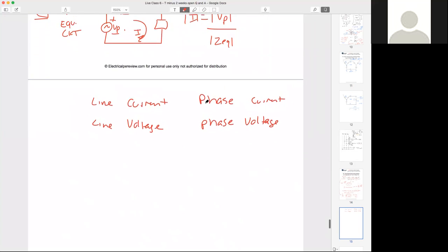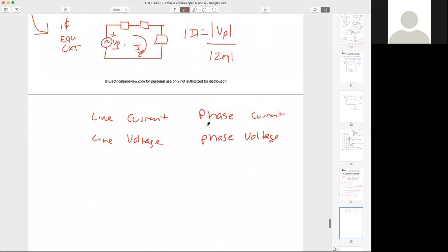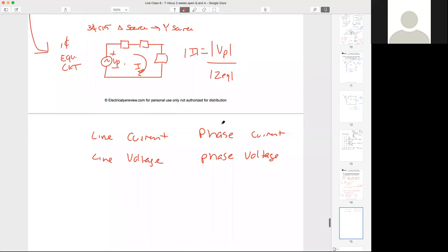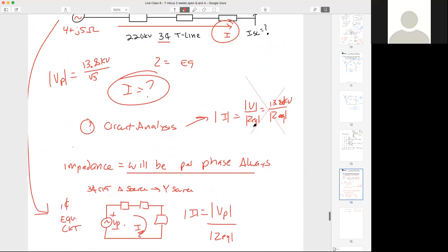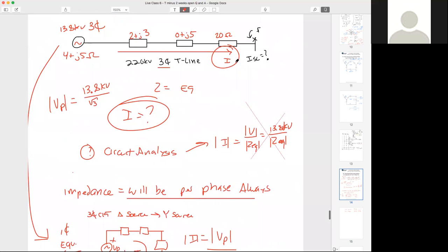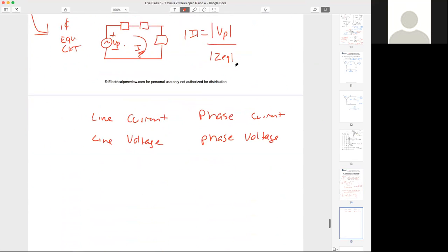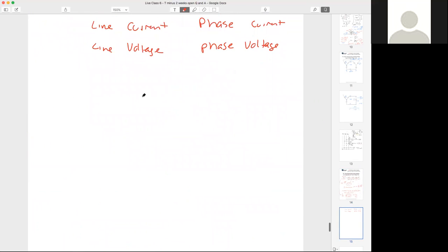Shamil said, so I short circuit is always per line. Would we never have to add three-phase currents for a fault? No, Shamil, you would never want to multiply your line current by 3, because this I right here, our line current, is the individual line current on each of the 3 phases. Let's draw this. I think this is going to be an eye-opener for some of you.